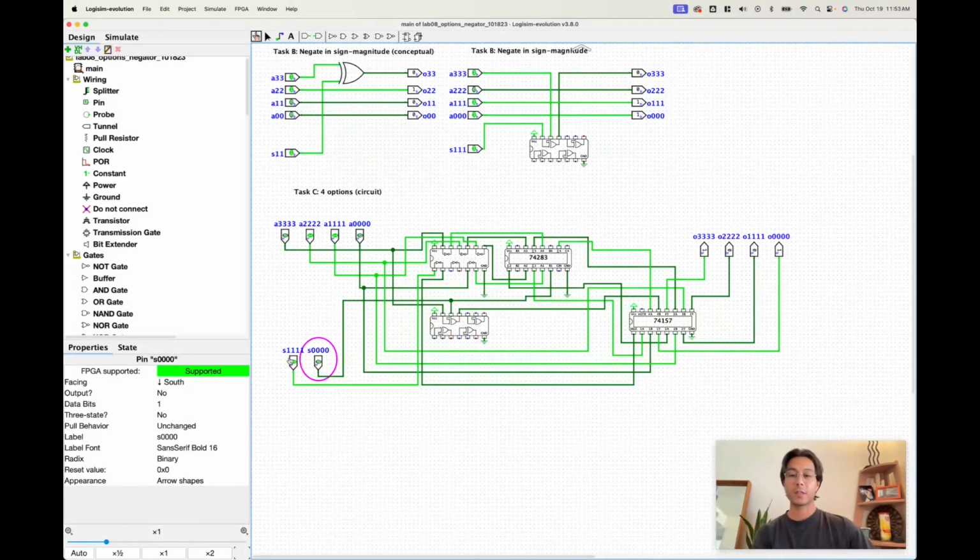And then S1 is plugged in through a NOT gate here to make it active low, the way we routed this in the A and B in the final IC here. But this is essentially choosing at the top line the first of the nested if statements. Once the selection of the nested if is created, then it goes on and does the final selection of the selection that was previously made here in the final chip and then outputs that.